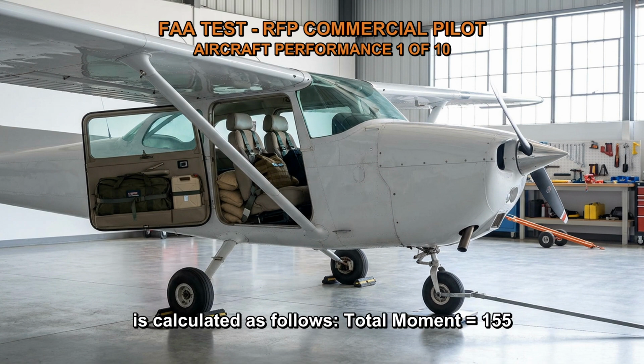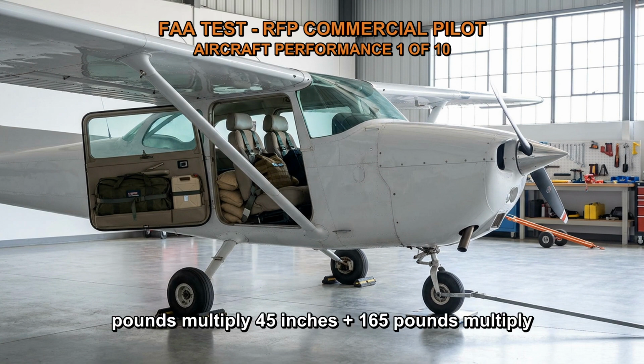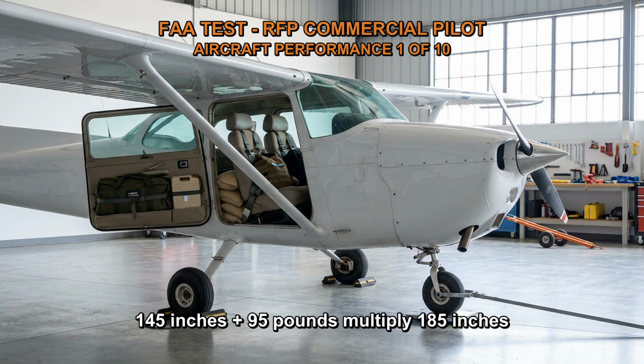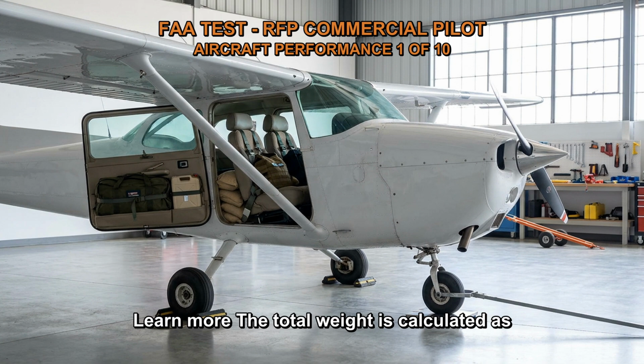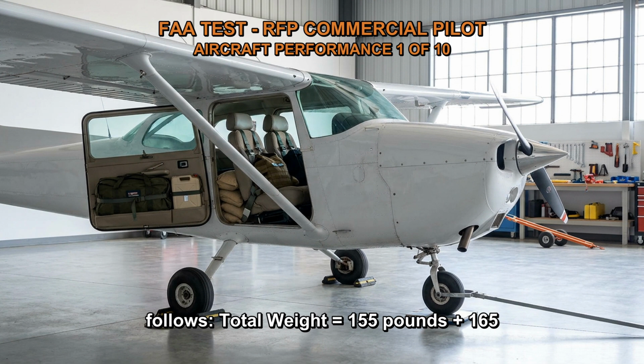The total moment is calculated as follows. Total moment equals 155 pounds times 45 inches plus 165 pounds times 145 inches plus 95 pounds times 185 inches equals 28,675 pound-inches. The total weight is calculated as follows. Total weight equals 155 pounds plus 165 pounds plus 95 pounds equals 415 pounds.